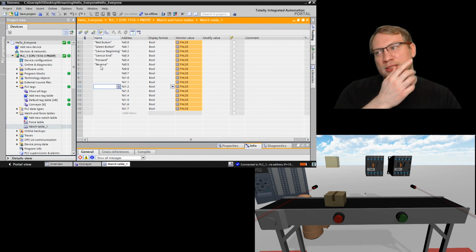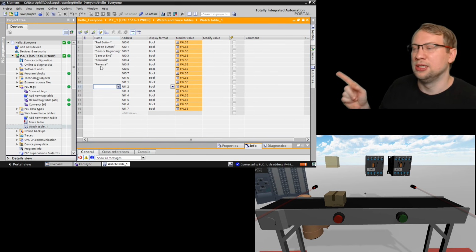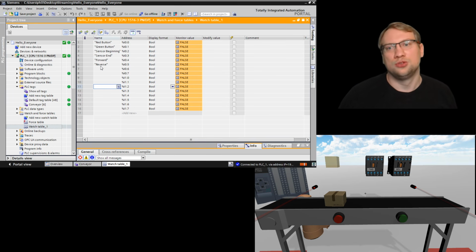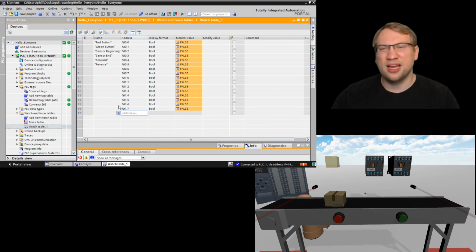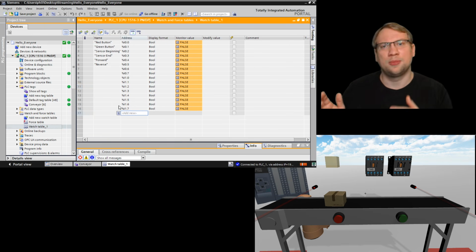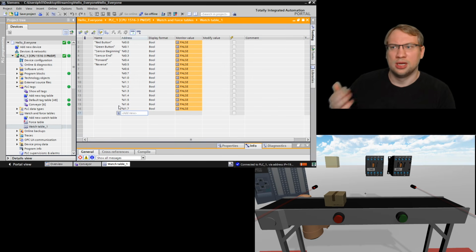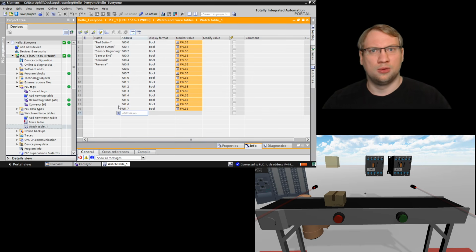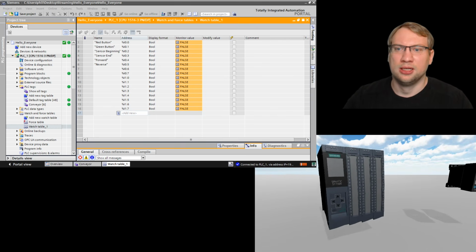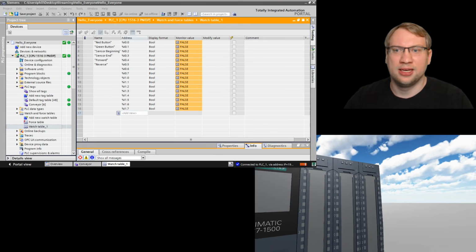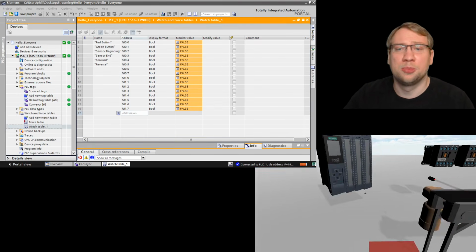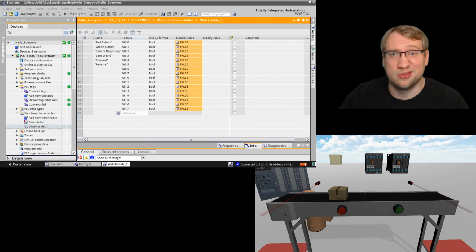So in my watch table here, I can also create outputs to test the system. I know that this conveyor is somehow from output 0.0 until output 1.7. So basically, I know it's somewhere on this line here. It is connected somewhere, but I don't know where because I did not make plans and I haven't written it down.